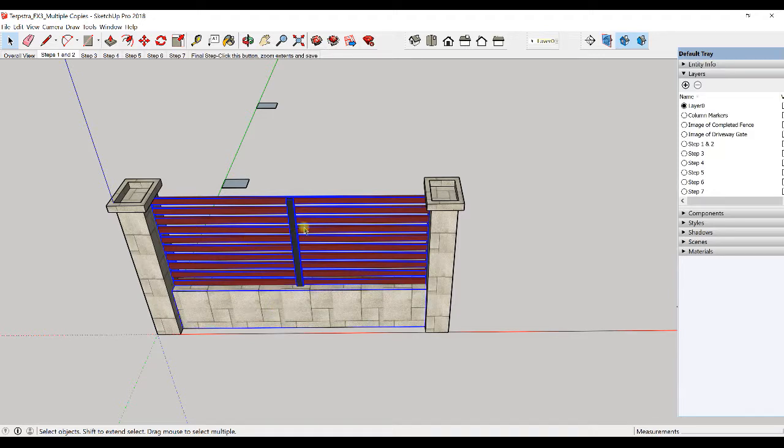So I need to have all 4 grouped objects selected at once. All right, then I'm going to copy them so they're right next to this column, to the right of this column, just as all of these are to the right of this column. I'm going to activate my command, hit M for move, Control for copy. Does my cursor have that little plus sign?